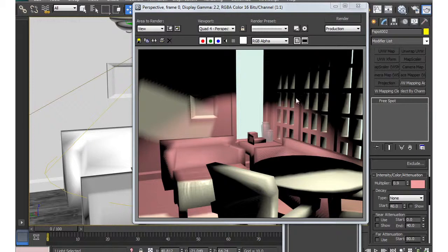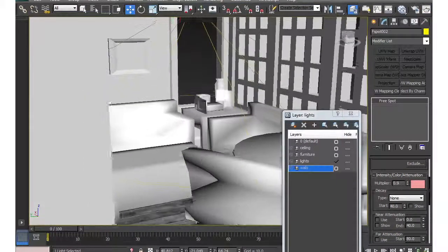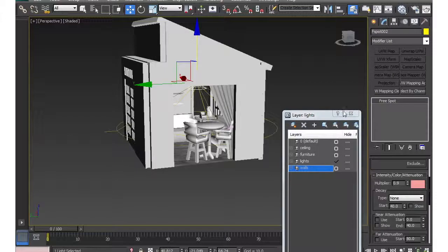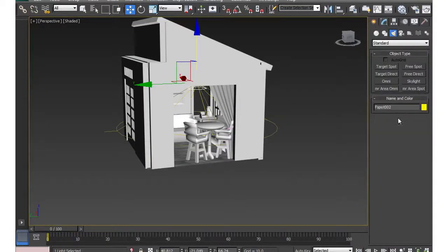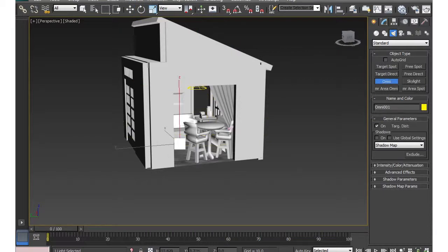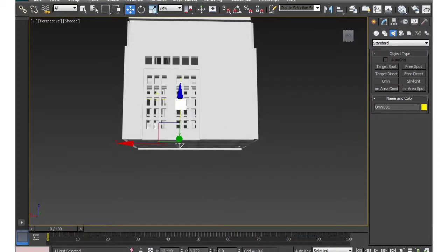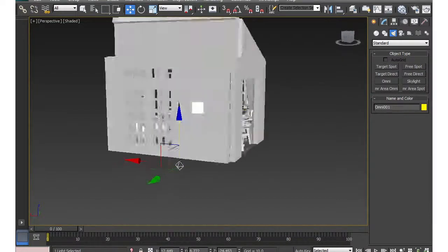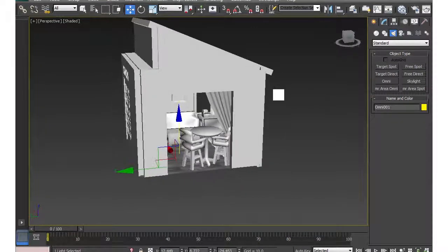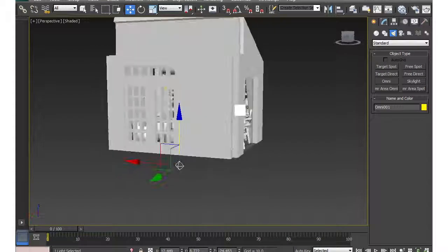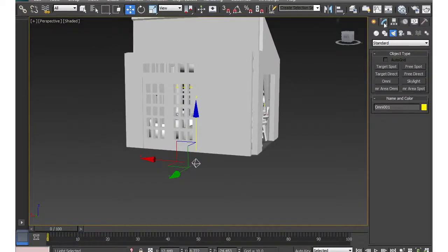We're certainly getting a warm hue in here where the spotlights are casting. But above we get nothing. And so what we need to do is we fake a bounced light. We can do this by either grabbing an omni, putting this in the room. In fact, we can put it below the room and have it cast its light upwards. Or we can get a spotlight and have it shine up. For now I'm going to use this omni.